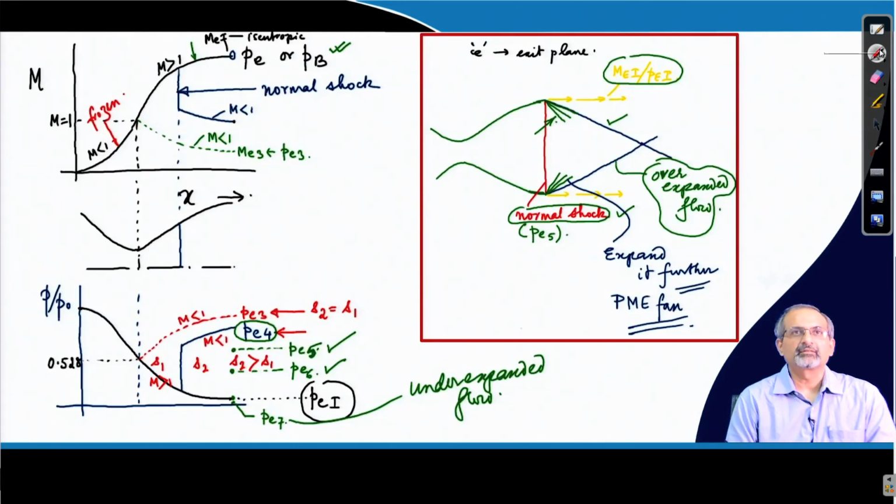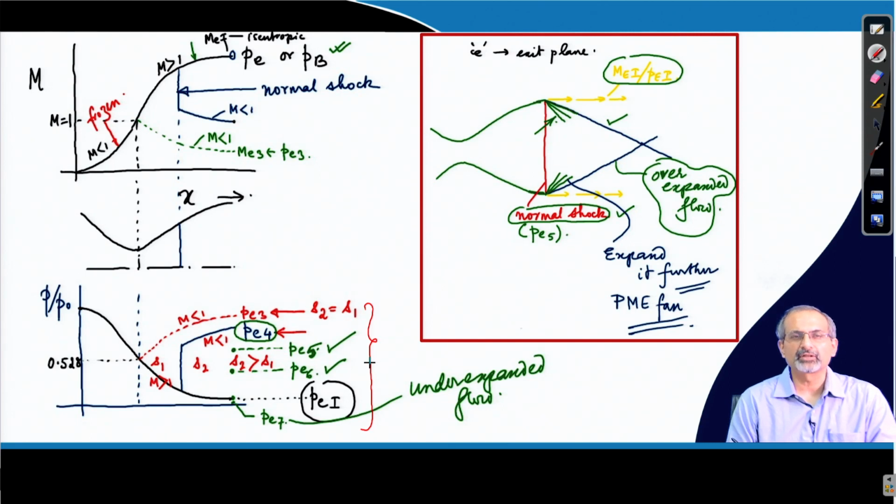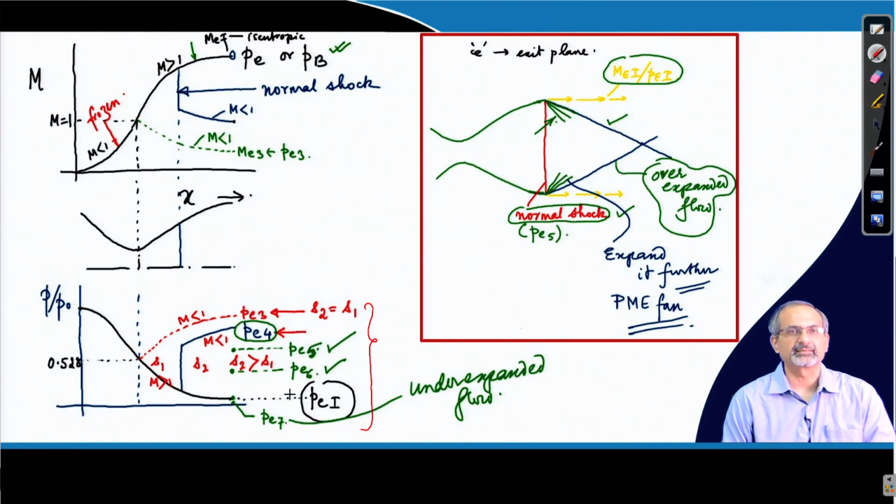So, these are the figures which you may recall, where we had discussed about changing the back pressure or exit pressure and then trying to look at how it impacts the flow within the CD nozzle. So, we discussed about different possibilities. Different pressures can create isentropic or non-isentropic situations, and here in the case of supersonic wind tunnel, we are of course interested in having the isentropic conditions through the CD nozzle, so that we have a very stable supersonic flow through the test section.